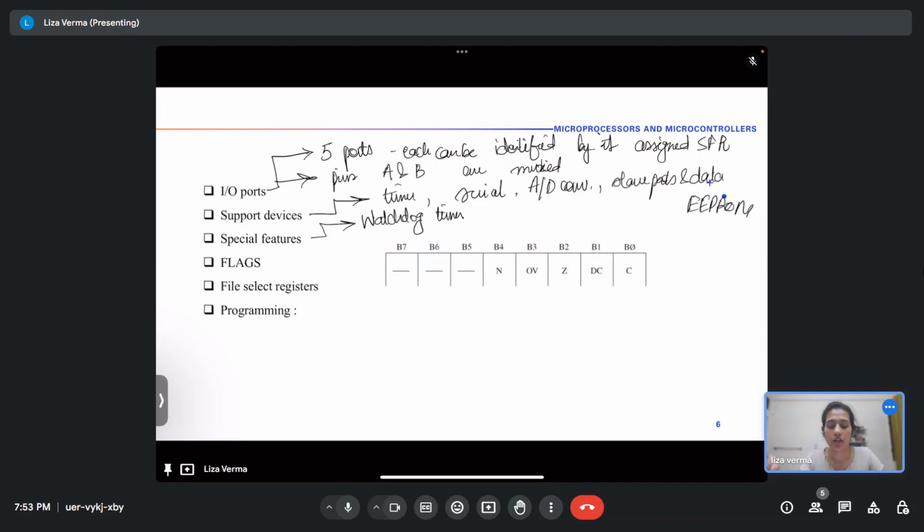But let's say your system is not able to regain or prevent or get over the failure, or get to normal functioning in the right time. That's where your watchdog timer comes into play. Let's say some failure occurred, and this watchdog timer will start the counter independent of your system clock.